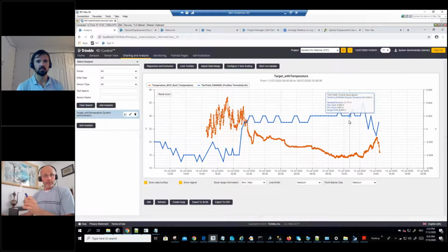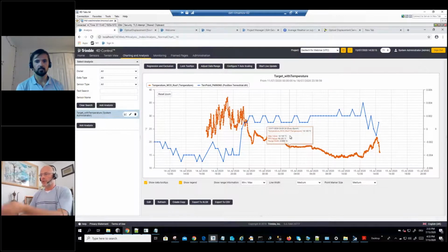So in this case, it's a geodetic, so a total station observation, and a geotechnical or a temperature sensor. So you're kind of combining the two in a way. Right, you can combine with some moisture content, or I don't know, some tilt sensor, just to make sure, okay, you have values from totally a different sensor which are matching with the movements, which means that they correlate in the time. There's correlation in the time, and you can be sure, yes, everything is fine.